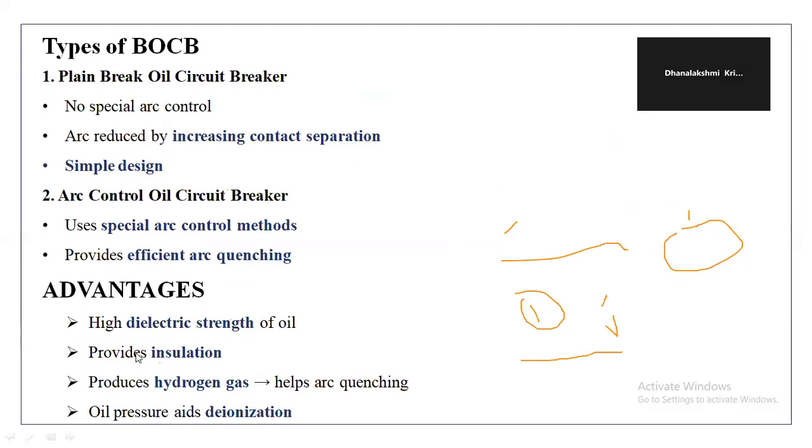So some advantages are there. It has a high dielectric strength of oil, which provides insulation, and produces hydrogen gas, which helps the arc quenching, and the oil pressure aids decomposition.